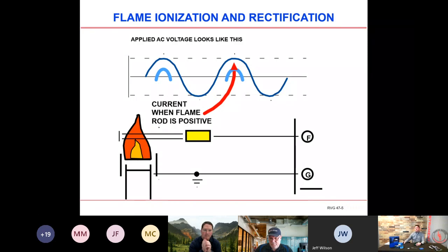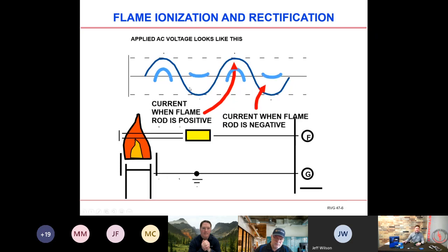If you have a Honeywell flame relay, like an RM7800 series, that signal is actually amplified and shows up as a voltage in the display of the RM7800 series. That display shows 0 to 5 volts, with the bottom threshold being 1.25 volts. On the bottom side of this curve here, we have about 1 microamp.